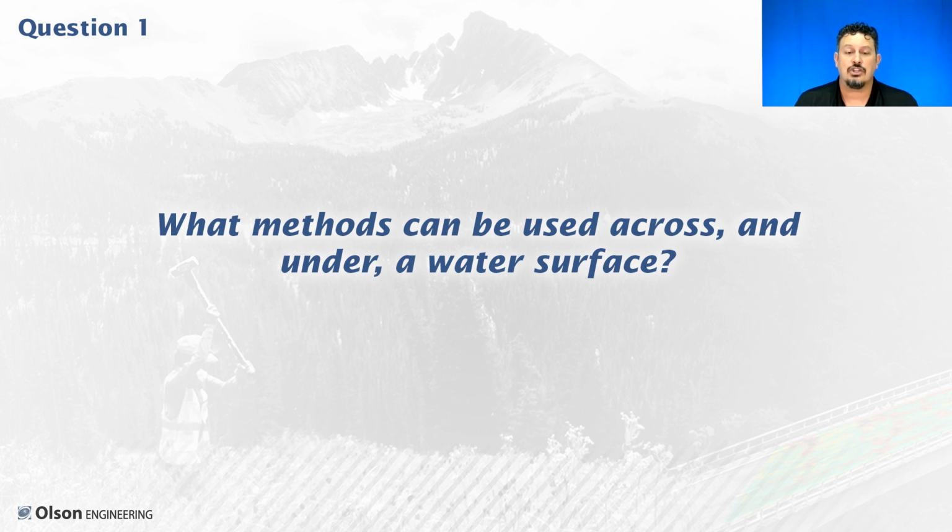And then I've done lots of GPR bathymetry surveys where I'm pulling my GPR system around a lake surface in a little rubber boat behind my boat, and using that to image both the water soil interface at the bottom of the lake as well as below that. It just depends on the electromagnetic properties on how deep you can see. So I don't know, hopefully that answered the question.